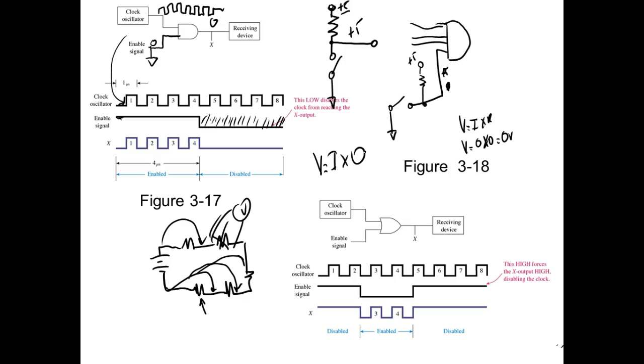How much voltage should a fuse drop if it's good? Pretty close to 0. It's going to drop a little bit because it's got a little bit of resistance. That's the way it blows. It blows because of I squared R. But it's going to measure really, really close to 0. Good job.